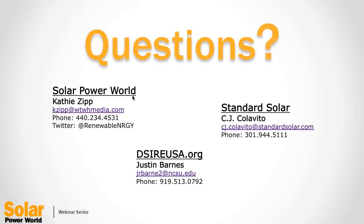I would imagine that it really depends on where the PV system is relative to where an available point of interconnection with the grid is. So primarily that requires you to know where the power lines are running and what voltage they are, and is it an available interconnection point, and where is the customer's electric service, or where is the load with that meter measuring that customer's demand relative to your body of water. But I wouldn't imagine you'd want to go through the body of water, but going around it or avoiding it would make a lot of sense.